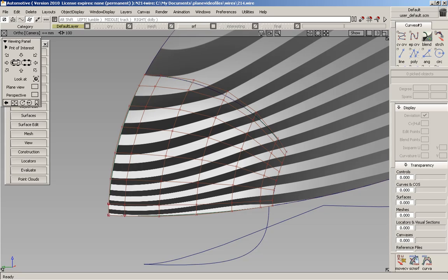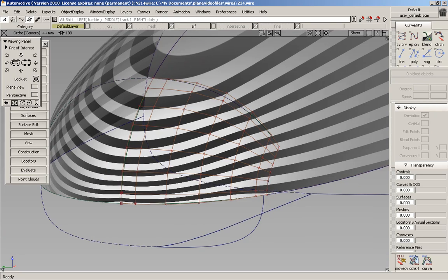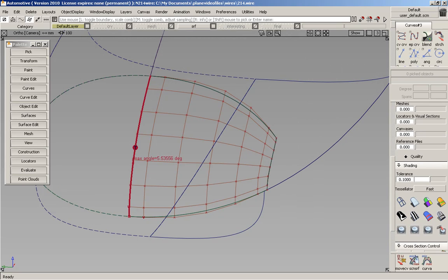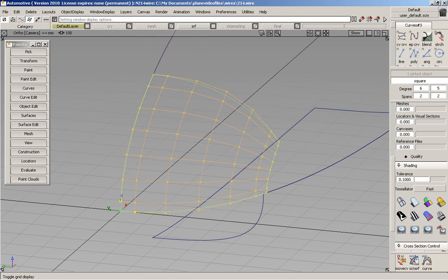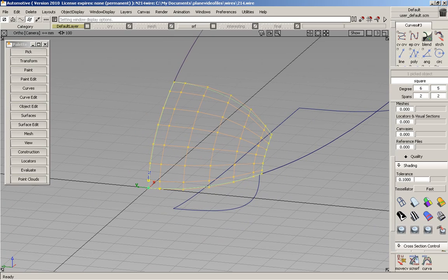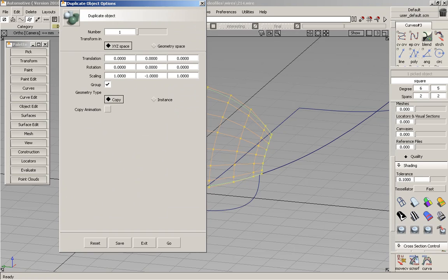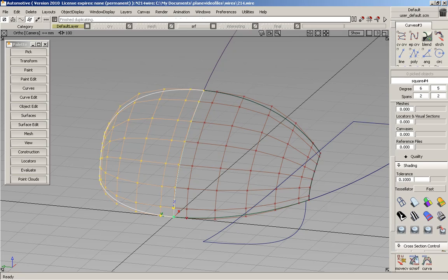So what we're going to do now is, if we go ahead and apply this on a layer, you'll notice that there's probably a curvature break here in the center, and there is. So I'm going to turn symmetry off, turn our grid on, and set my pivot at the origin, and we're going to use the duplicate object tool. I've set it for -1 on the Y, and we're just going to flip that over.